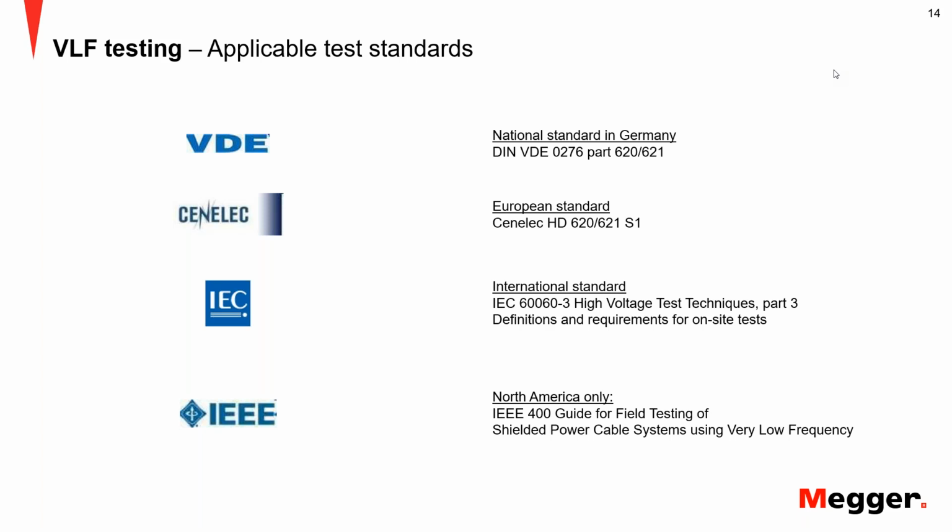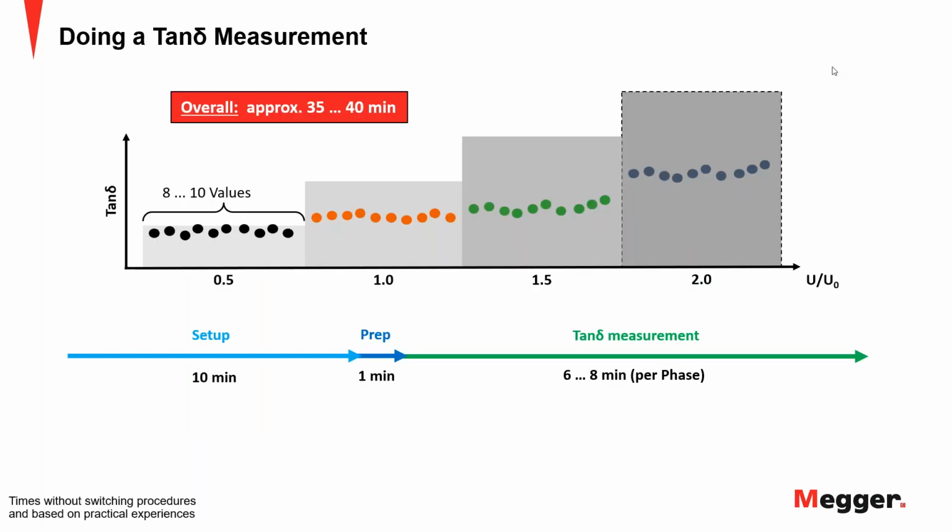You want to do a diagnostic test way below where the cable could fail. So that's why there are two, like Robert is saying, totally different tests for different reasons. And you're trying to also see different effects in the cable. One is for the aging effects, and the other one is for a pretty severe defect that would fail on a hipot test.